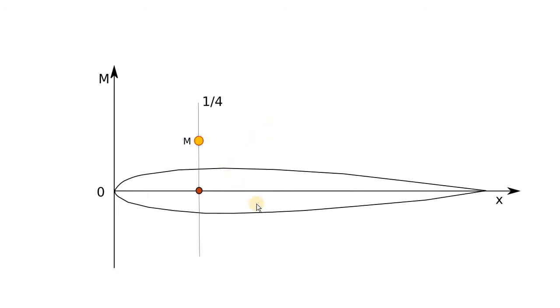We can say this airfoil is not good for the flying wing and so on. But in reality, the absolute value of the moment is completely irrelevant. If we move from the zero-dimensional creature to a one-dimensional creature, living on this line, on the chord line, we can compute the moment at each point, and then we're going to have those beautiful lines.